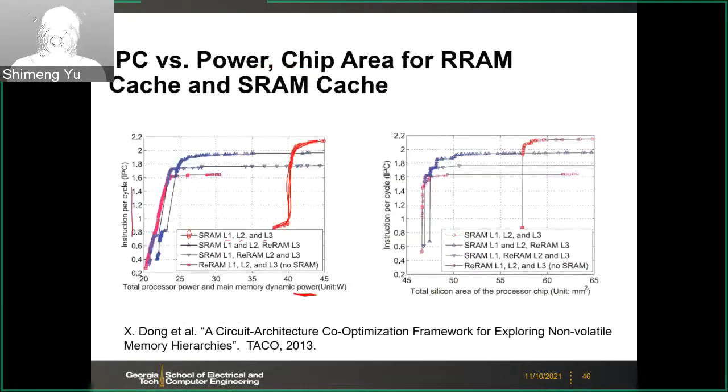So you still have different design options for SRAM. And typically SRAM will have higher IPC, as you see here, because SRAM is faster, right? But with SRAM's power, if you consider the leakage power in the real workload, then this is system level power, including your ALU, your compute, and the cache and also the main memory power. This kind of processor needs like 40 watts, but you do get higher performance.